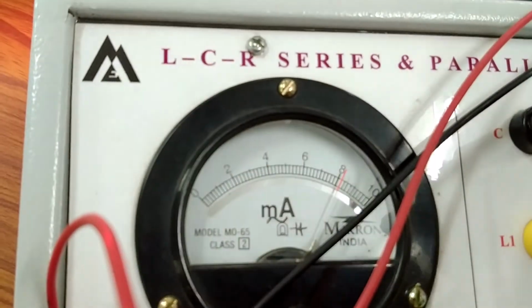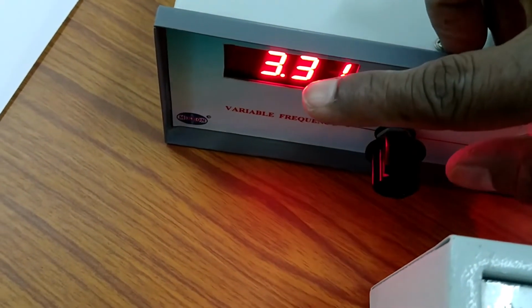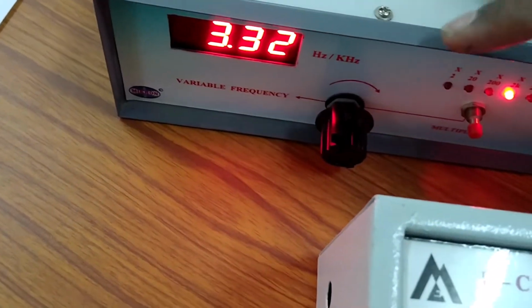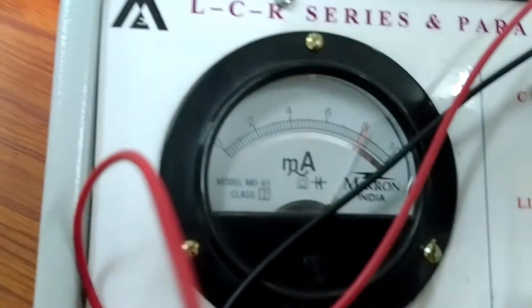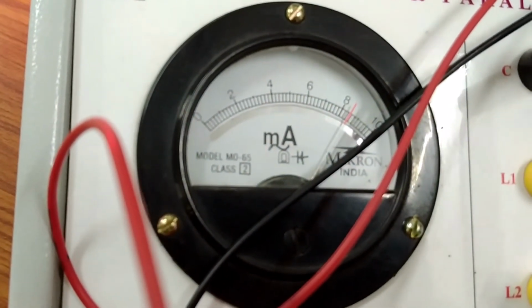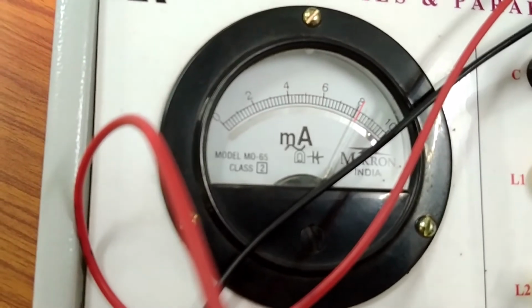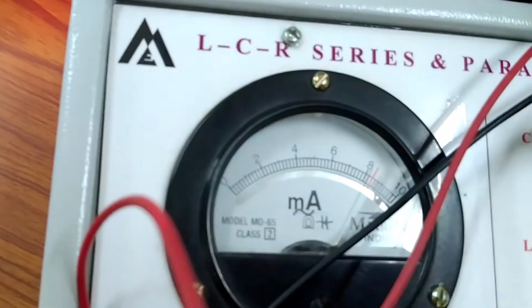So now the value of the frequency is 3.31 or 3.32 into 2 kilohertz. Then I note down the current value here. If I still increase, the current is still increasing. I still increase it, and now it is decreasing. So therefore I am getting the maximum somewhere here.